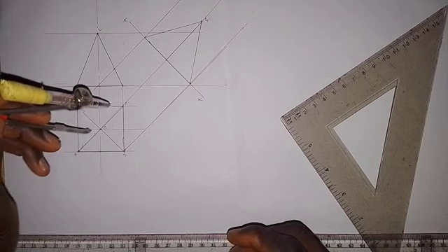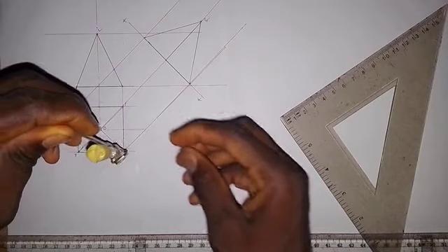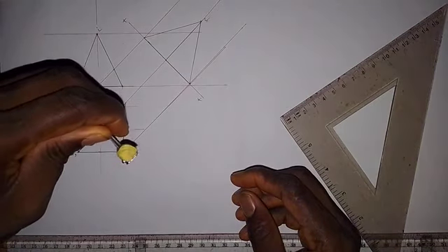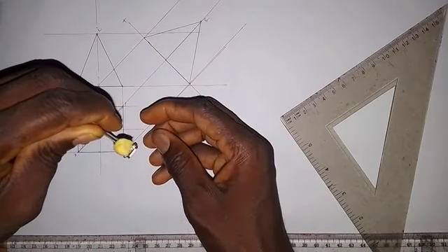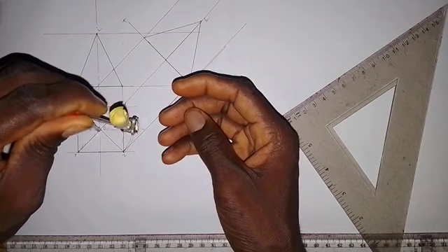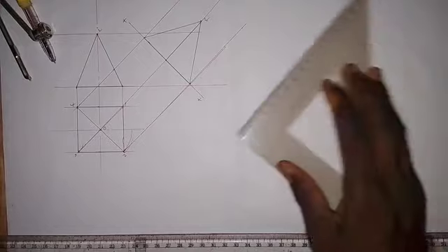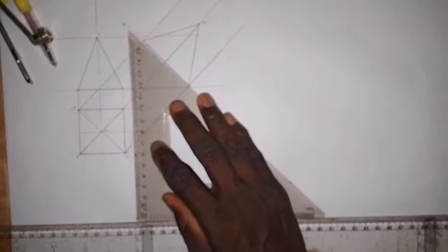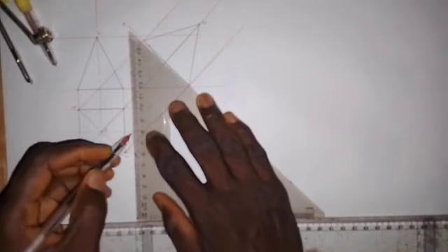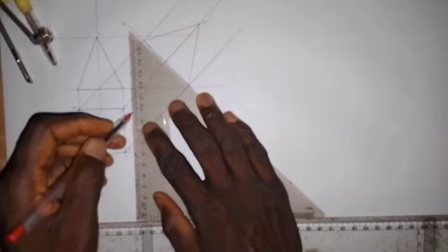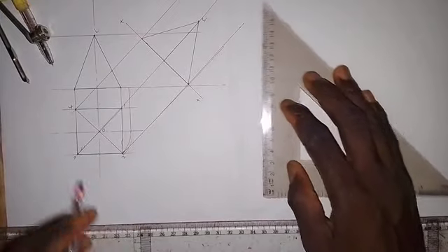What you need to do is to put the point of your compass at this point O here, then extend to point 2 like this, and draw an arc. We draw the arc from point 2 like this. Wherever it touches on this horizontal line that comes out from point O, you have to draw a vertical line. So from this point, where the arc touches the horizontal line, draw a vertical line to meet the horizontal line that is drawn out of the base of the pyramid here in the front elevation.